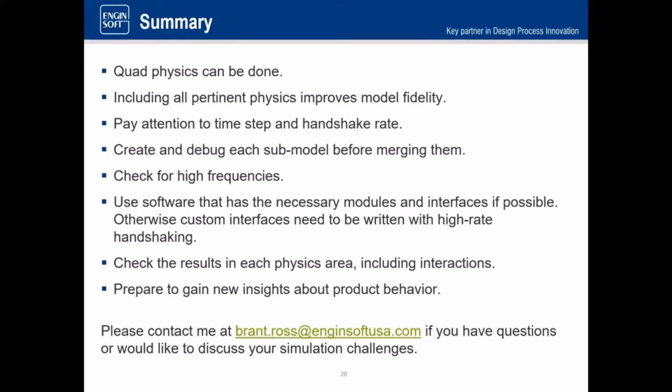Yes, it does. So this is the solver that's included inside of RecurDyn. And so it's a nonlinear flex body, and that flex body can actually interact with rigid geometry. And so then in all cases, the contact is using the element faces. And then the flex body to flex body would be one set of element faces interacting with another set of element faces.